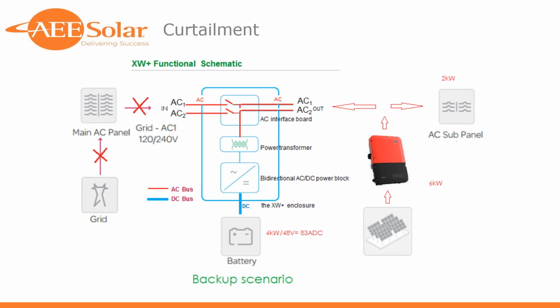And what would happen, they'd get the house on site, they'd set it up, they'd turn on some lights and things, and in the day, the array would start to produce power. If the loads were not sufficient, the battery inverter would fill up the batteries, and this being a very small battery bank, the battery would fill up very quickly, and the battery inverter would then turn off the array.